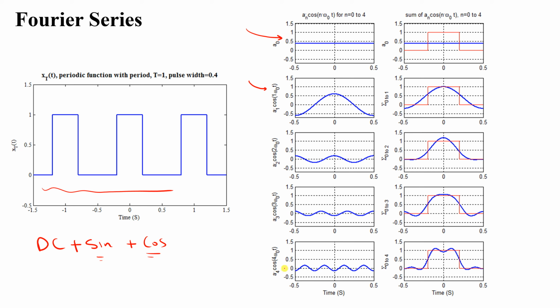Now the fourth component, or four times the fundamental frequency. So it will become closer and closer like this. You can see it became close to the signal. Now if you get the fifth component, 6, 7, 8, 9th, and so on, you keep adding it until infinity, you will be very, very close to this rectangular shape. Okay, that is what Fourier series do.